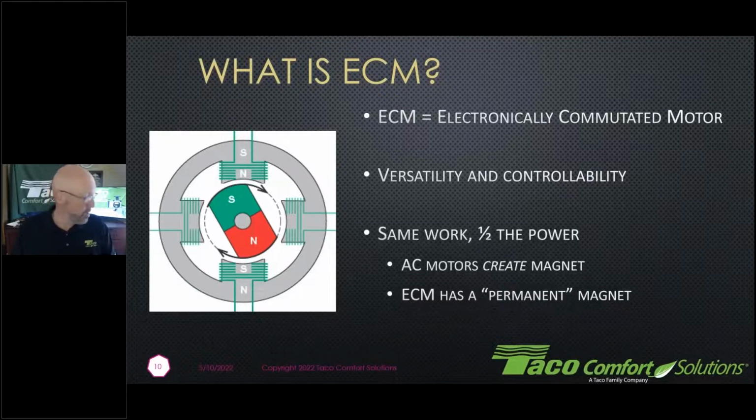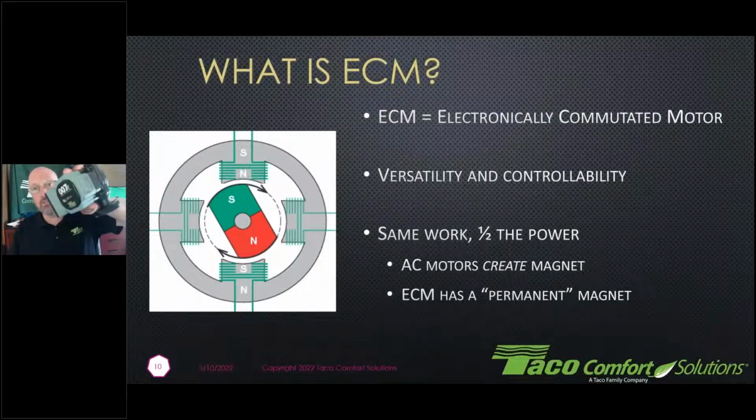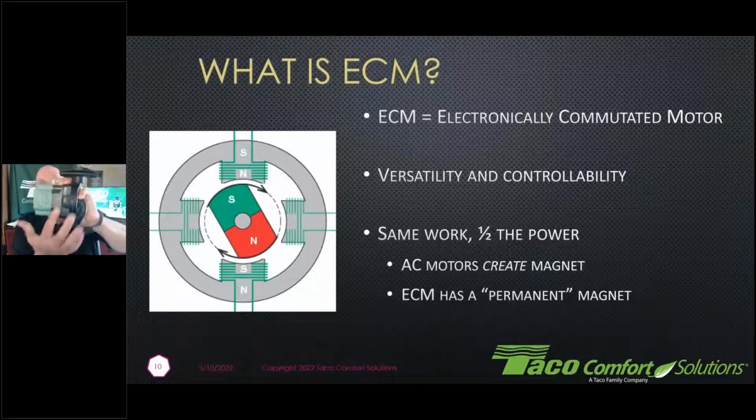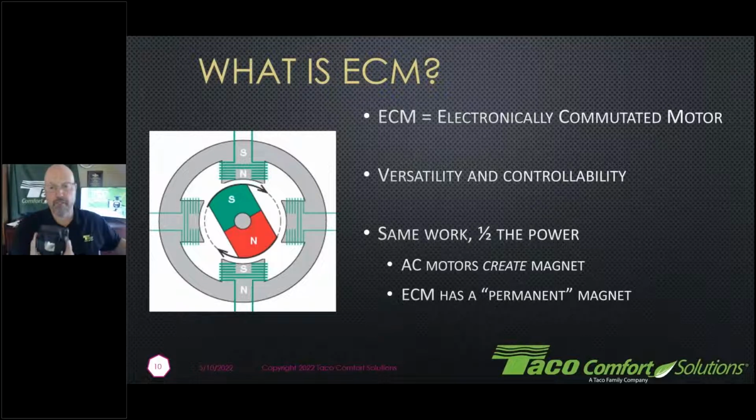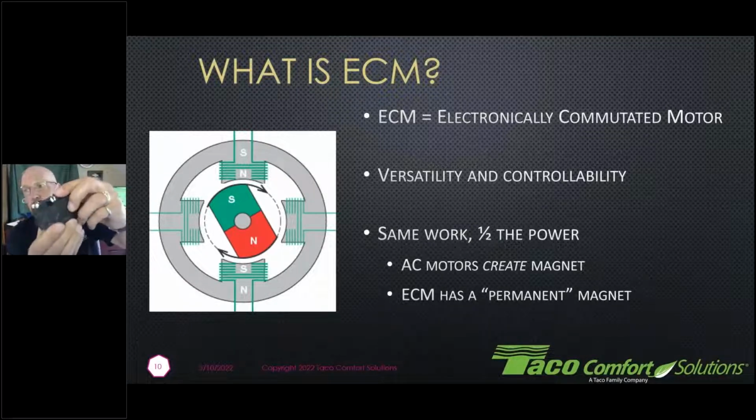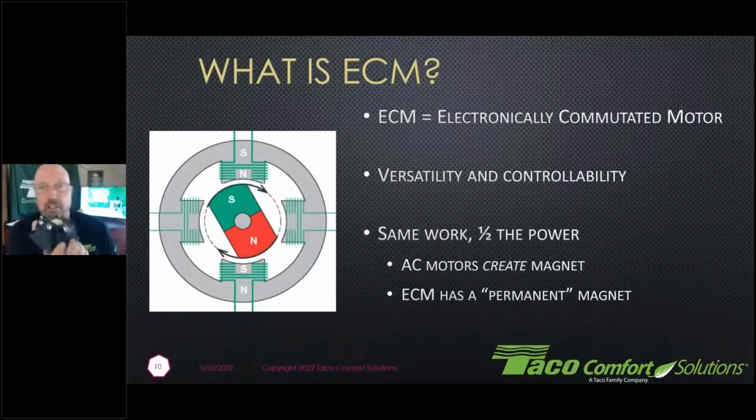drop into that circulator. So when we just look at the manufacturing of an ECM circulator, for example, here's my standard 007E ECM. When you look at it from the side, this black part that you have here in the camera, that is your motor. That is the entire motor. The green part here has our circuit board in here, and then the circuit board is mounted on top. Now I do have the motor separated here, so here we can see the motor, and right here are some terminal points where our circuit board lands on top of here and then creates the poles in order to make